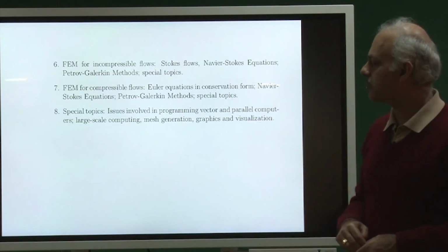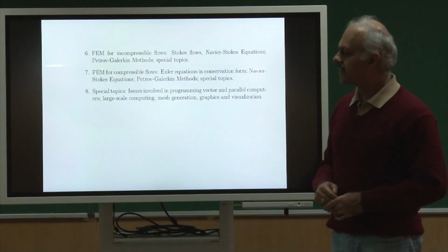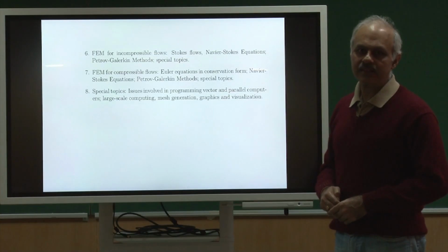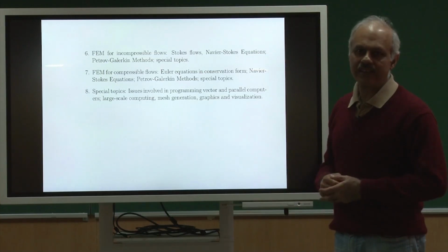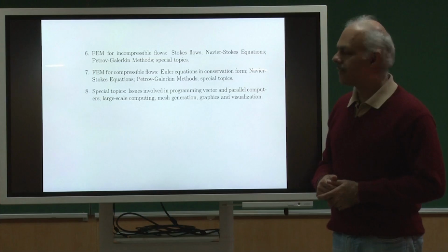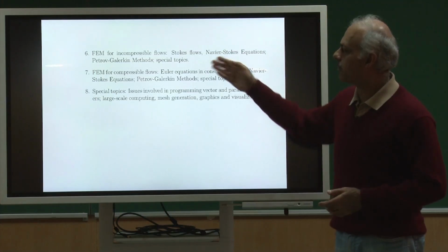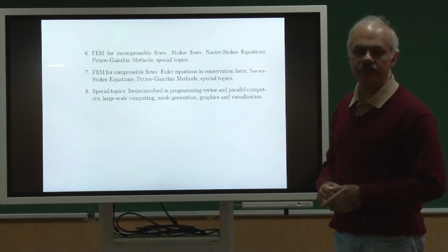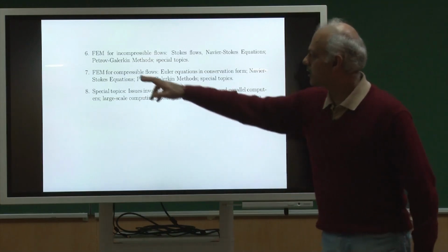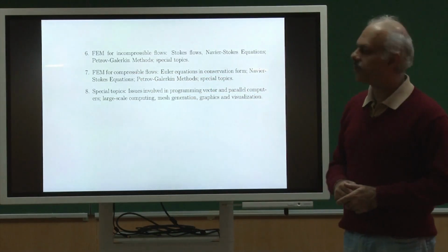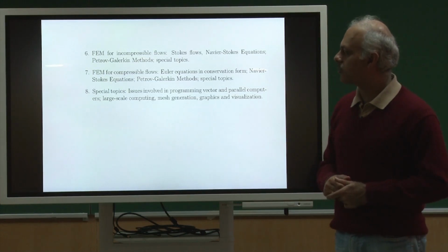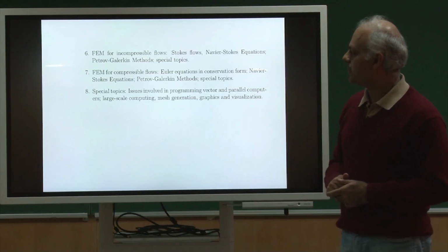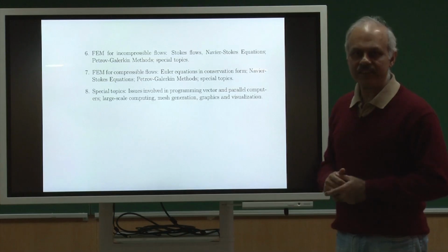Of course, it will be rather brief. What we will realize is that the traditional Galerkin method, which works very nicely for heat conduction problems, is not going to work for flow problems, both for incompressible and compressible flows. So we will have to deal with some new kinds of framework called the Petrov-Galerkin methods. I don't want to harp on it right now, but when the time comes, we'll see that these are very clever modifications to the Galerkin method to make them work.